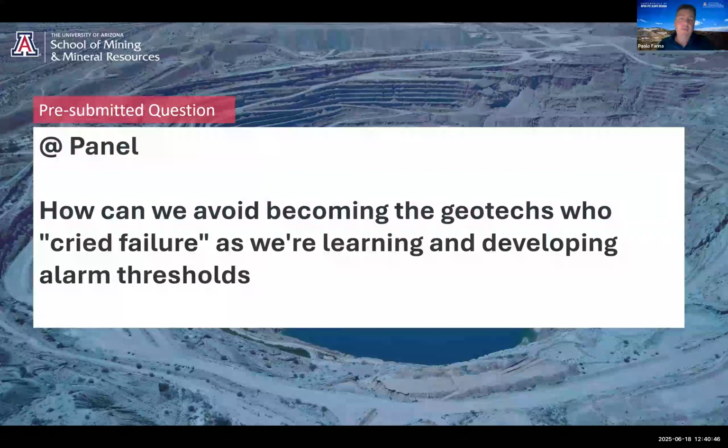Of course, again, we are assuming that the failure is developing over a time interval compatible with the analysis done by an expert. And in general, when it comes to defining automatic alarms capable of evacuating an area, it comes to me the idea of defining an acceptable rate of false alarms with the operation. I mean, we should define how many alarms per week, per month, in your opinion, the production team is able to accept, no? Without losing trust in what we are doing.